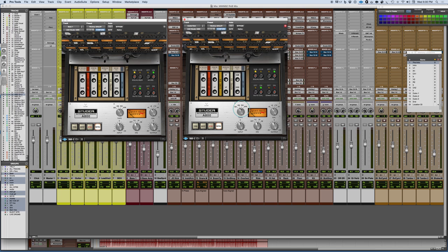If you had one tape machine, a 24-track tape machine, 16-track, whatever it was, you had one speed, one tape formulation. You could do on some machines multiple alignments on different channels, although that was more likely to lead to some kind of problem down the road with some maintenance person who misunderstands what's going on and then tries to re-record your tone reel or something like that, and ends up being something disastrous. So you would end up just by default picking a tape speed, because you couldn't have more than one tape speed on individual tracks. You have a tape speed, a type of tape, a tape formulation, a bias setting, your alignment standard, and you set it all up, and then you record, and you work that way.